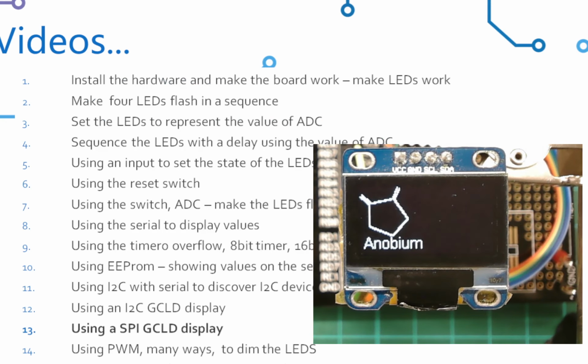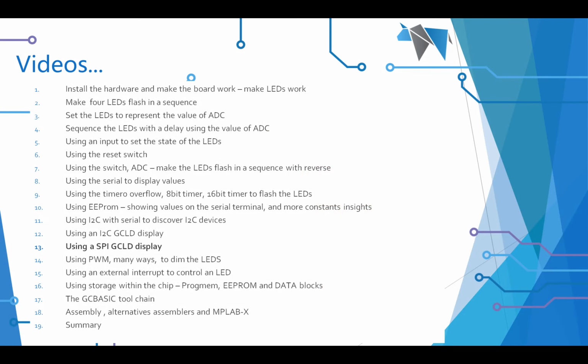So what I wanted to do is show you that you can use a GLCD in a very low memory device like this, or legacy devices still supported, and you can use hardware or software I2C. If it doesn't support it, the libraries support that, because that's a low level library. You simply tell it to use software I2C.